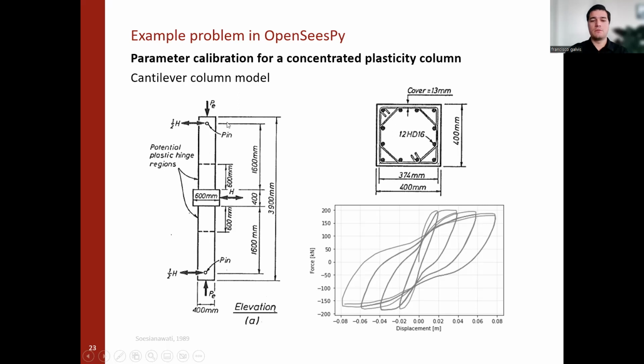One actuator responsible for applying axial force and one actuator responsible for applying lateral force, right? This one from left to right here. And the concept is that you will have that applied symmetrically on both sides, which theoretically then means that you can simulate only half of the specimen, since the response should be symmetric.